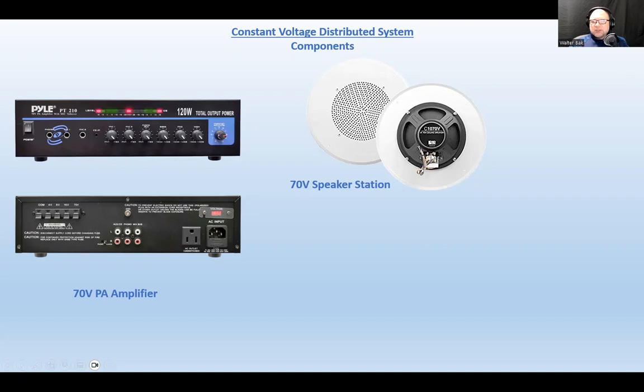And here is the step-down transformer with secondary windings of the transformer connected permanently to the 8-ohm terminals of the speaker. And over here you have one common and different taps that are going to be labeled as different power taps.